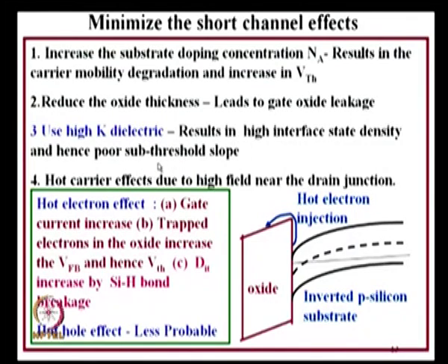So, you need to have some passivation techniques done there. Now, when you use high K dielectric, you must ensure that the energy gap between the conduction band of silicon and the conduction band of the dielectric is high enough. If it is not high enough, the electrons which are here can climb up here and get into the dielectric. In the case of silicon, they do get into that region when you go to large voltages, large electric fields.